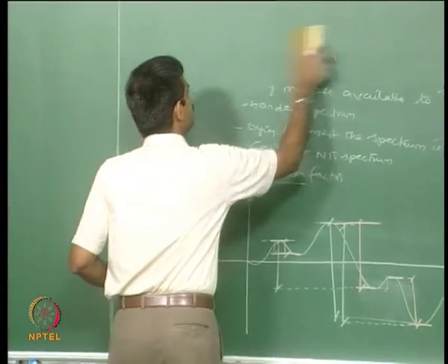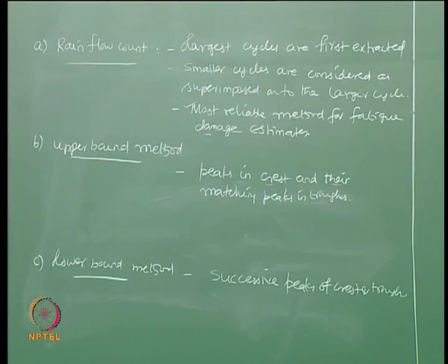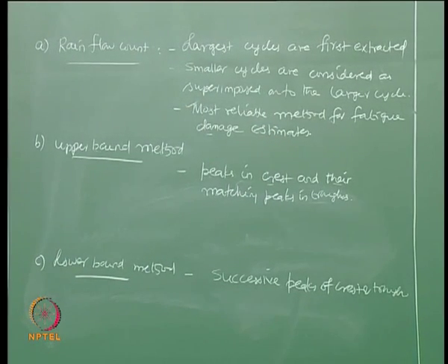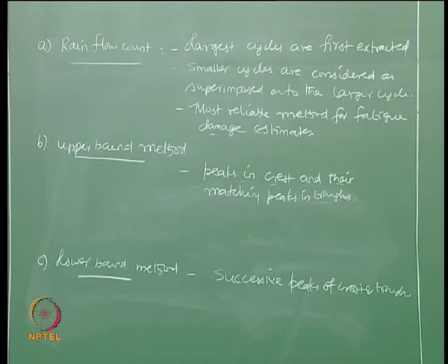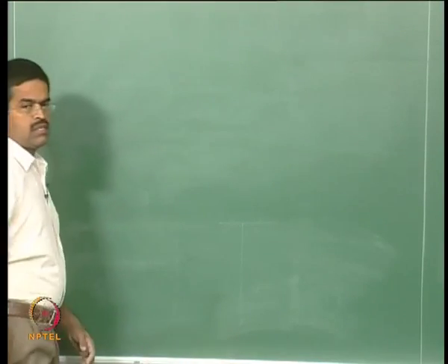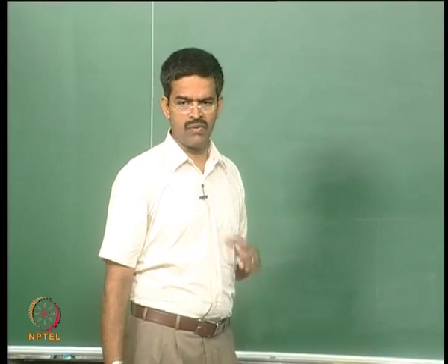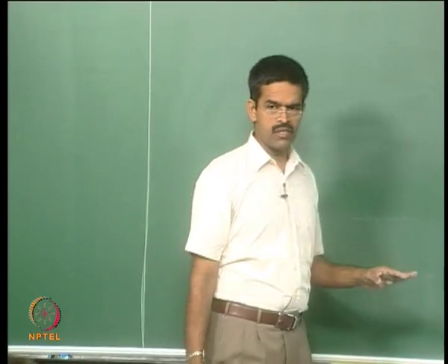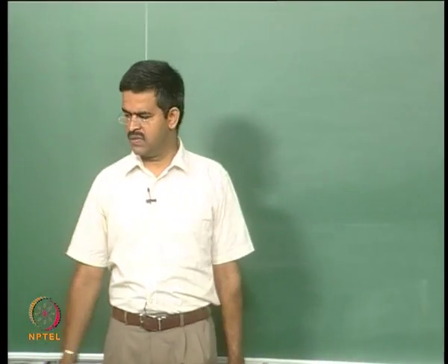As I said, once I do this, I would like to convert the given broadband spectrum to an equivalent narrowband spectrum, because this will help me to use the existing narrowband spectrum equations available to me for fatigue damage. I will apply a correction factor to this suggested by various researchers.